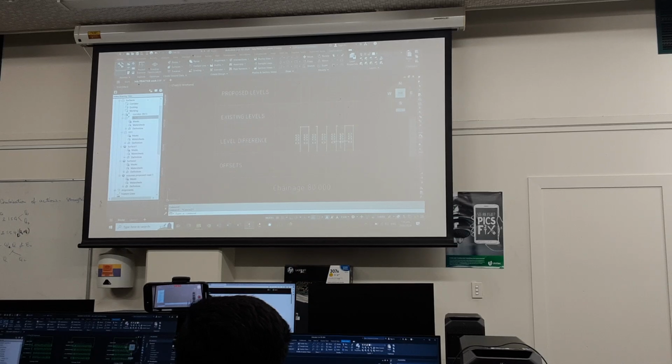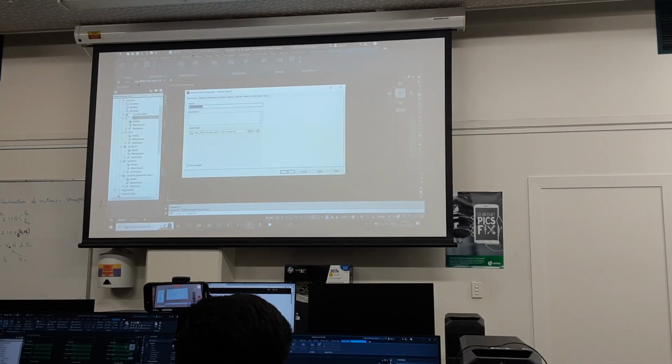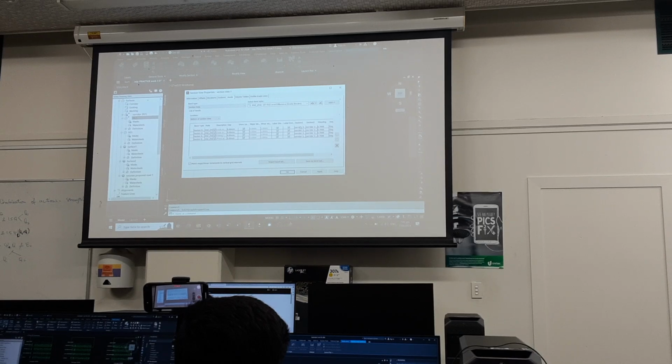Okay, can you click on that and right click, section view properties, and then bands, like we did in week 1. You've got to do them all. Section 1 is the EG1. They're both set for corridor. If you have to change them all, it's going to be really annoying, so I wonder if there's a better way to do this.